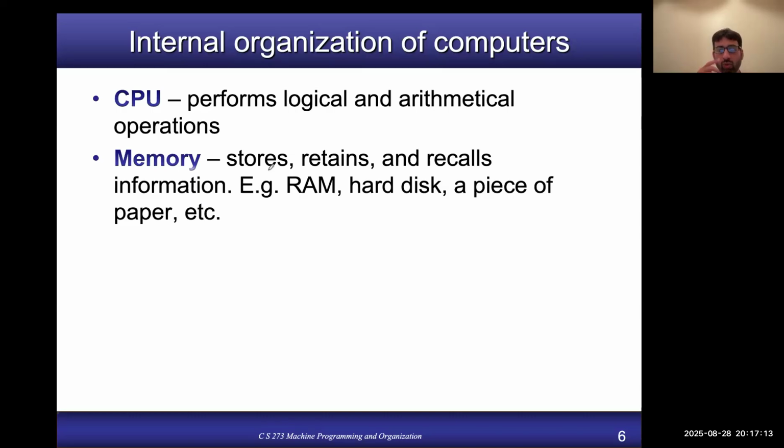All the numbers on which you want to do any kind of processing are read from the data memory, and after you perform the processing, the results are written back into the data memory. However, instructions which you are executing are read from the program memory, and program memory is read only. You cannot write it during the program execution. Definitely you can burn it in the initial phase when you are downloading your program to the program memory of the AVR.